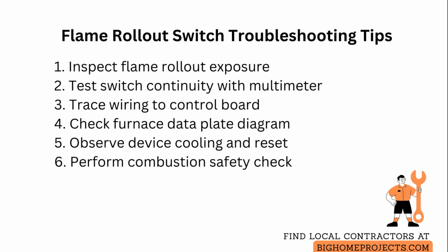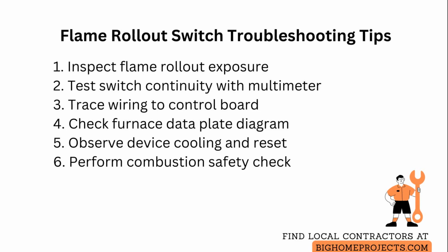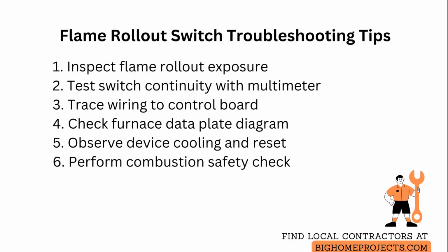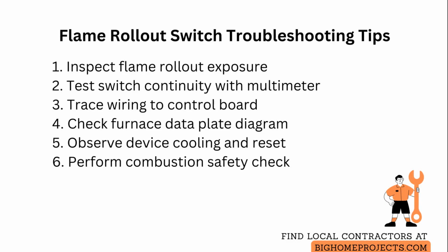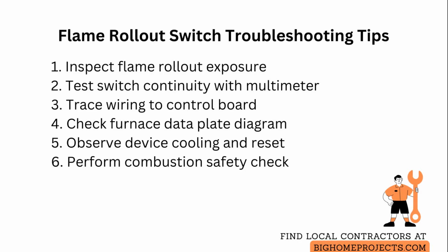Technically, the switch is a normally closed thermal device that opens when exposed to excessive heat, and then either latches open or signals the control board depending on the design. If the control board interprets the open circuit as a call for continuous ventilation, it will keep the inducer or blower motor energized until the circuit is restored. Check the wiring diagram on the furnace data plate and trace the switch wiring to confirm whether it is wired in series with the blower relay or to a continuous run input on the control board.